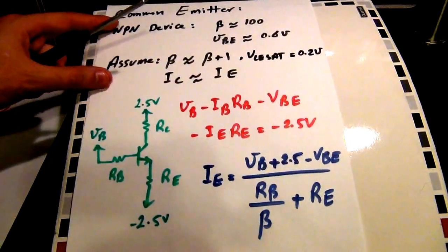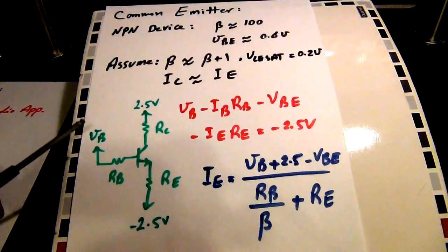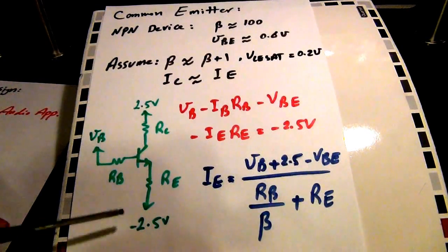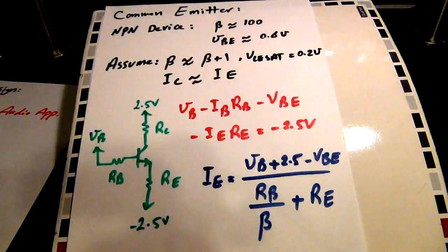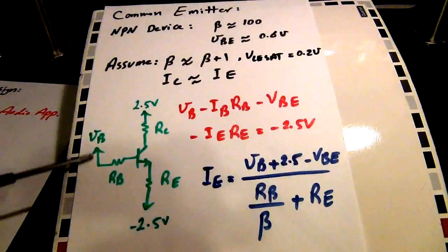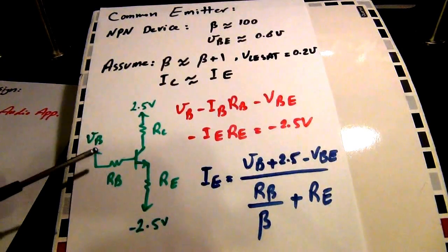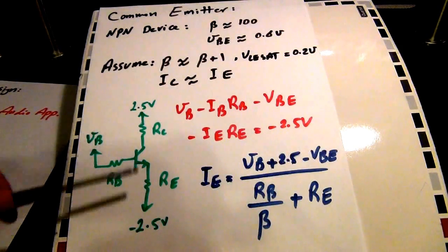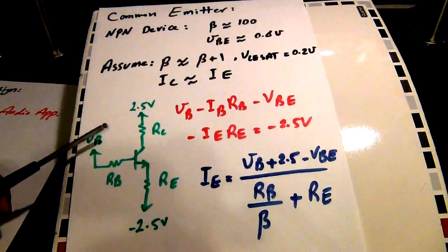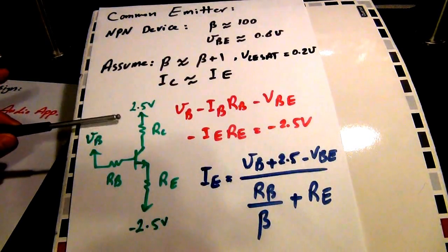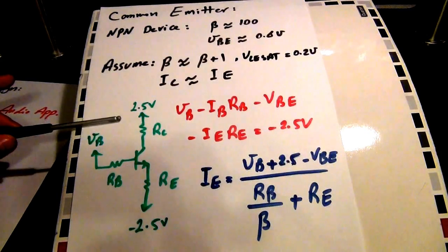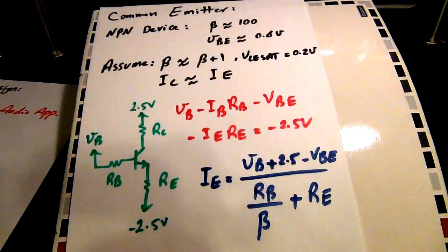So here I've reproduced the schematic of a very basic common-emitter amplifier. Here I'm showing the DC operating point. Now, what does that mean? With this schematic here, we are able to design the DC operating point of the amplifier, which is its bias current and all the voltage distributions between all of its components. If we don't do this step properly, if we don't choose a correct DC operating point, then the small signal or the AC behavior of the amplifier is going to be very poor.